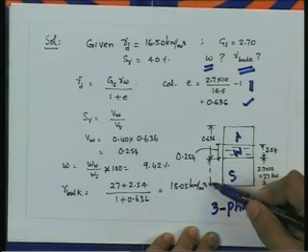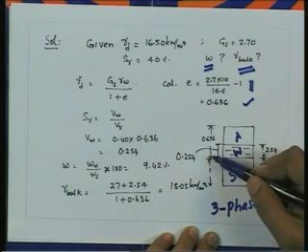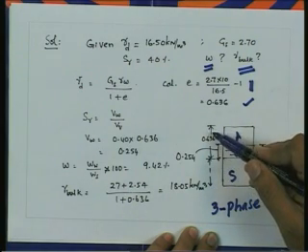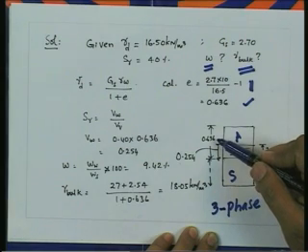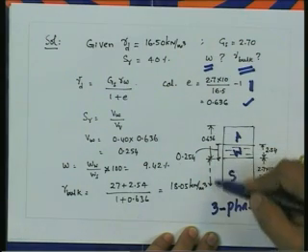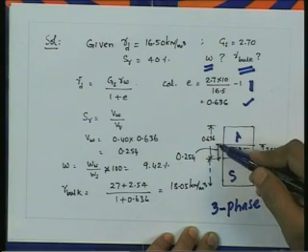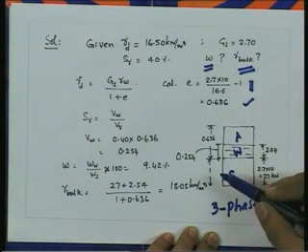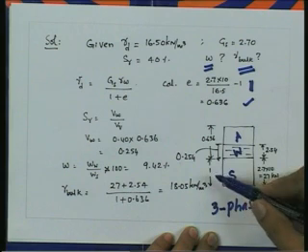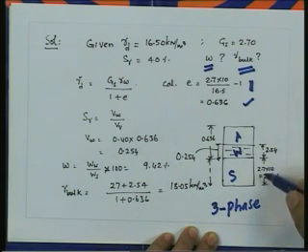By setting volume of solids equal to 1 and the rest as volume of voids, the void ratio is equal to 0.636, so total volume is 1 plus 0.636. From volume of solids as 1, by knowing the specific gravity of the solids, we can determine the weight of solids as Ws is equal to Gs Vs gamma W, as Vs is equal to 1. By knowing Gs is equal to 2.7, we can write Ws is equal to 2.7 into 10, that is 27 kilonewton.